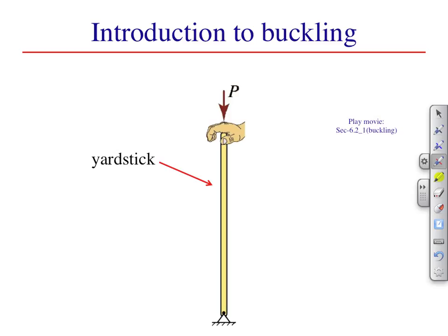In the summer of 2007, a span of bridge across I-35 near the Twin Cities collapsed suddenly. We can think of this as a kind of environmentally assisted buckling failure. Here the traffic load was not necessarily increasing, but the geometric integrity of the bridge was gradually degrading from corrosion and other environmental factors. There was no warning when the bridge failed. People were simply driving across it one minute and plunging into the river the next. This illustrates why buckling is such a concern. No warning is given, and the accompanying collapse typically results in total failure of the structure and loss of life.